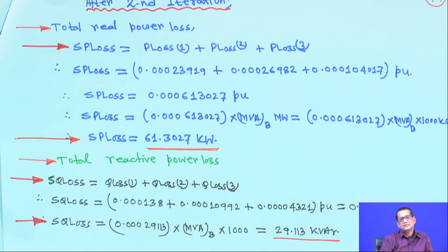One equation we wrote is I = (Vm1 − Vm2) / Zjj, that is, Ijj. Another equation is Pm2 − jQm2 = V conjugate m2 times Ijj. Using those two expressions, we can also get the angle delta expression, but in a distribution system the voltage angle is not that important. We have seen that the variation of angle is very small, that is why magnitude of voltage is sufficient. So, the second method will be better than the first one, if we need the voltage magnitude only.